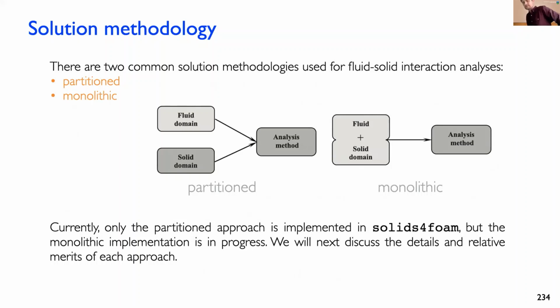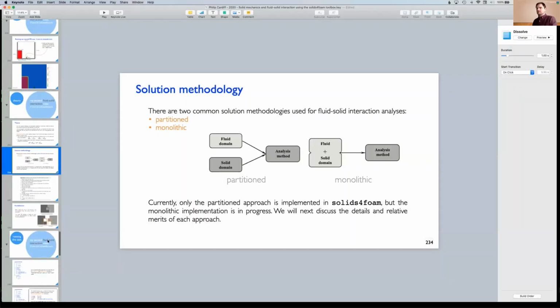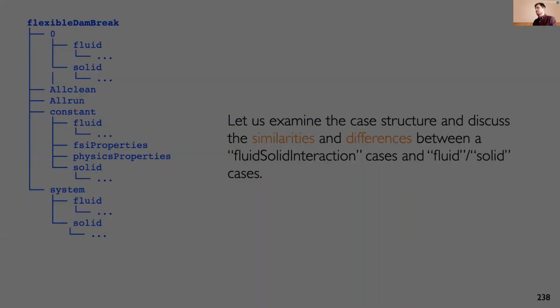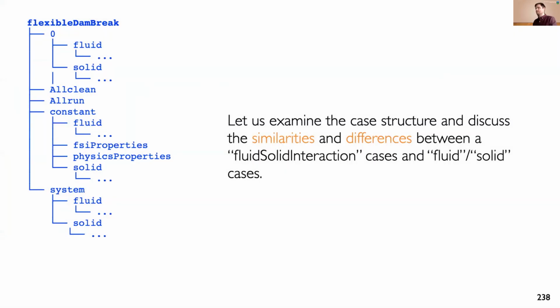There's many different FSI type procedures, well, 2 predominant ones. Partitioned is the most common one, where you solve a fluid case and then you solve a solid case and you pass information between them. It can be done monolithically, and it has to some degree in OpenFOAM, but I would say those procedures would need some development to make them generally useful.